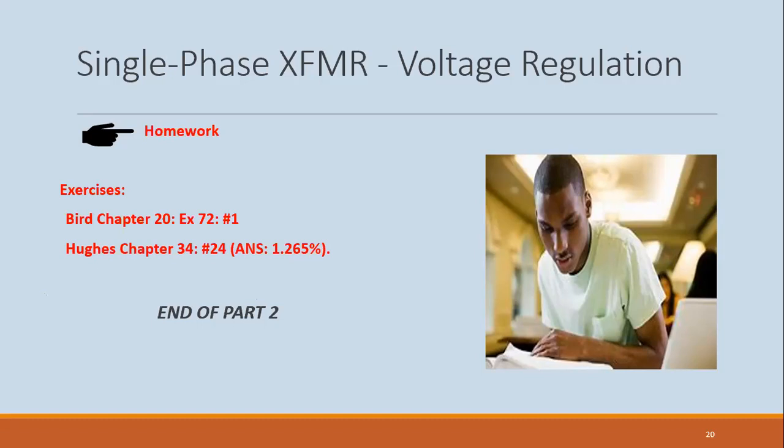The supply voltage didn't change. So remember, once you set the supply voltage, what you did was measure each of the phases. Ideally they should have been balanced, but we know that some of them weren't. It wasn't really balanced in terms of magnitude, but we assume the angles were still 120 degrees apart. We wouldn't have changed the voltage again.